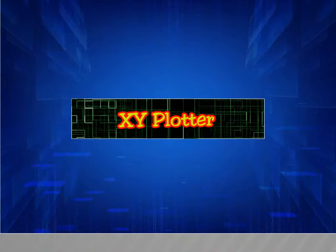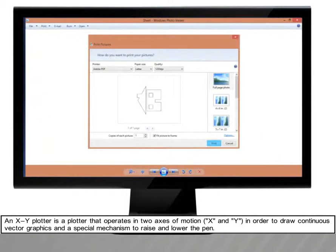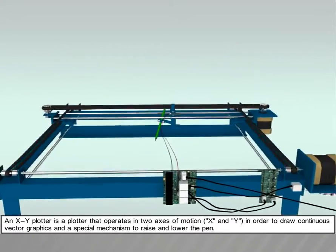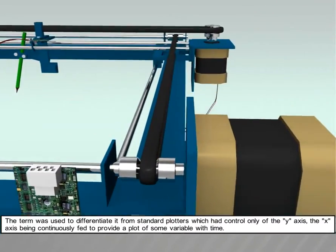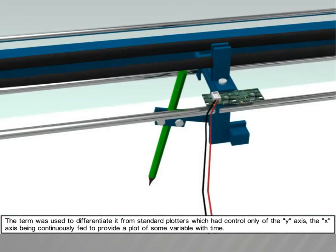XY plotter. An XY plotter is a plotter that operates in two axes of motion, that is X and Y, in order to draw continuous vector graphics, with a special mechanism to raise and lower the pen. The term was used to differentiate it from standard plotters, which had control only of the Y-axis, with the X-axis being continuously fed to provide a plot of some variable with time.